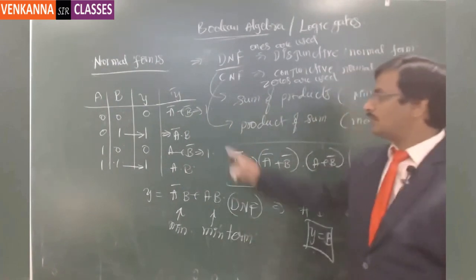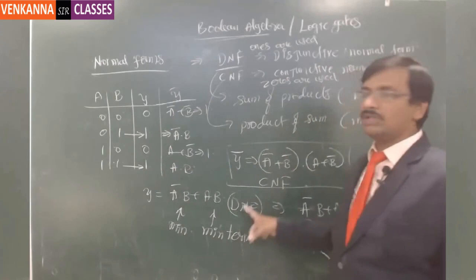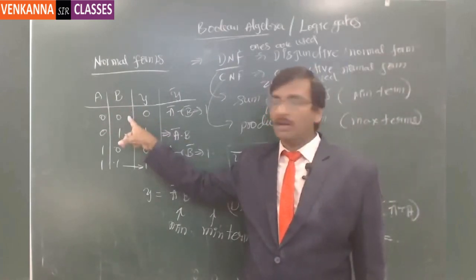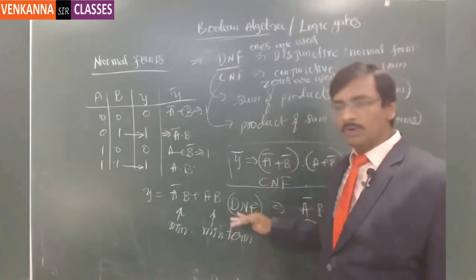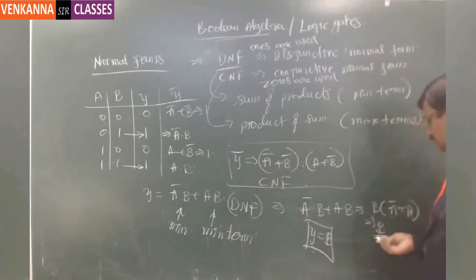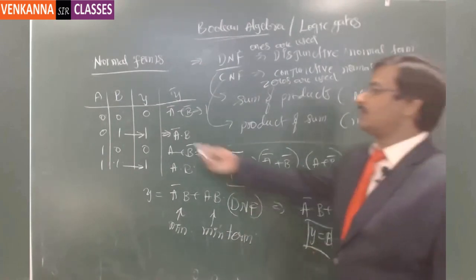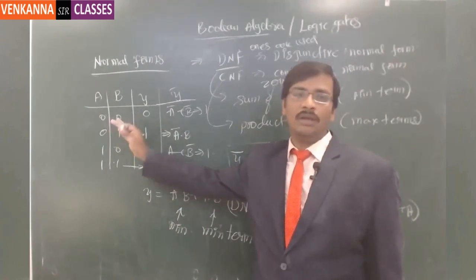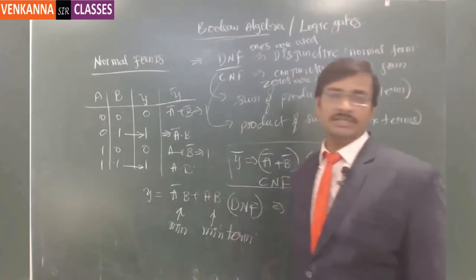So if you are expecting this kind of output, then if you don't know Boolean algebra, we would be worrying about both a and b. But with the help of these DNF and CNF forms, you constructed a Boolean expression which you are able to simplify to a normal form, the simplest form, and this is coming out to be b. Then for the user, you can directly suggest that don't worry about a, ignore a and take the output as b directly, and that will be your design.